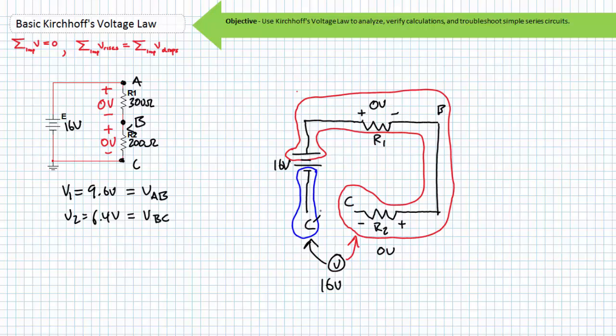In the case of an open at node C, I have to introduce an additional node I'll call C prime. The 16-volt drop occurs between node C and C prime, meaning that node A, B, and C are all at 16 volts, and C prime is at 0 volts. A, B, and C all being at 16 volts means there is no differential between them.